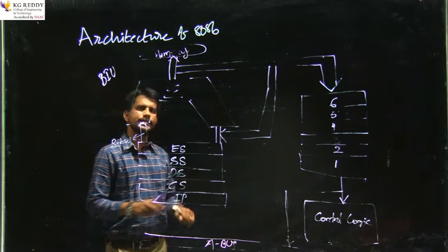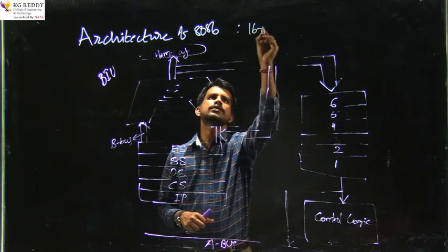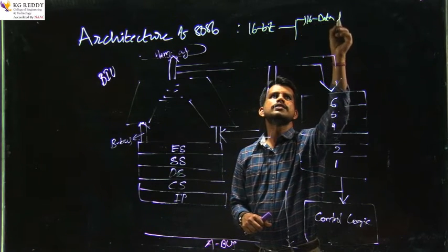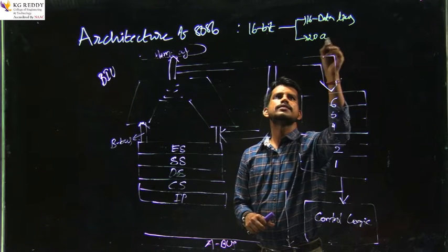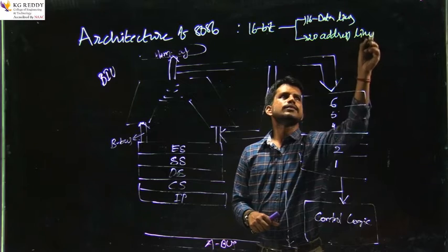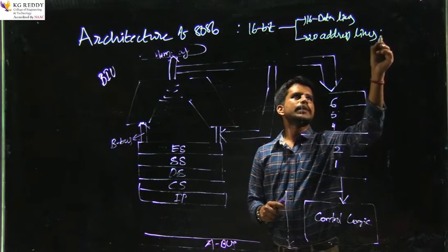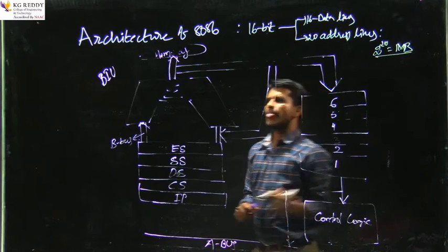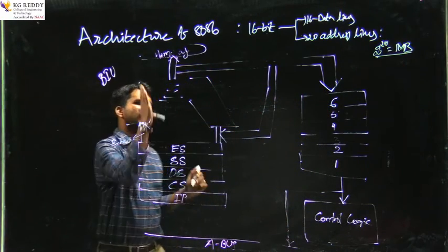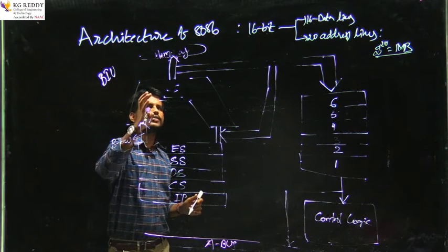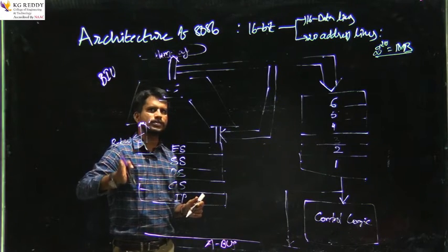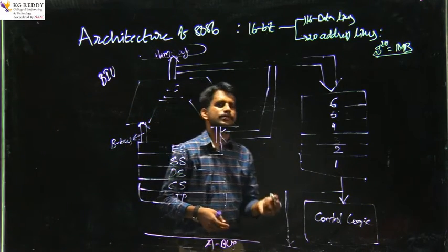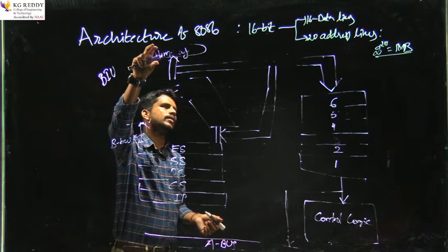As the 8086 microprocessor is a 16-bit microprocessor, it consists of 16 data lines and 20 address lines. And since it has 20 address lines, the memory capacity of the 8086 microprocessor is 2 power 20, that is equal to 1 MB. So, a maximum of 1 MB of memory can be accessed by the 8086 microprocessor, where we can store data like program code words and instructions, temporary data or resultant data, and data required for the running of a program, etc.